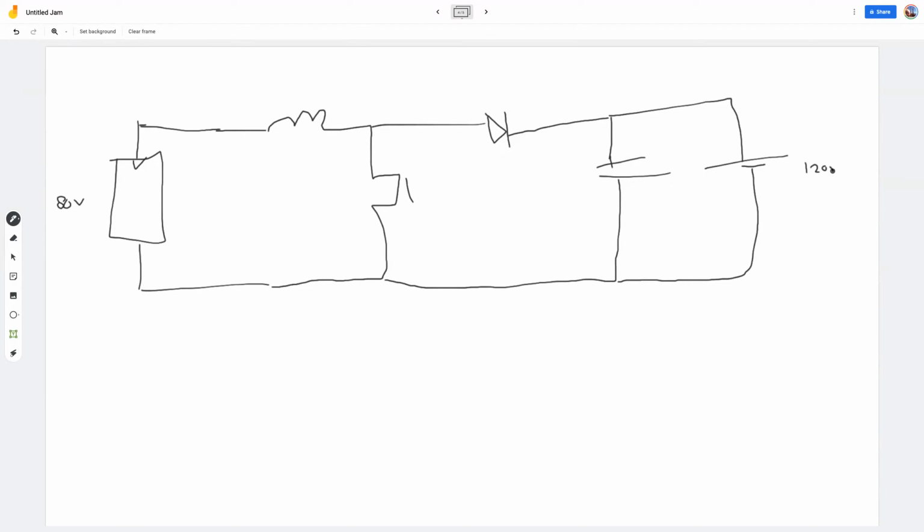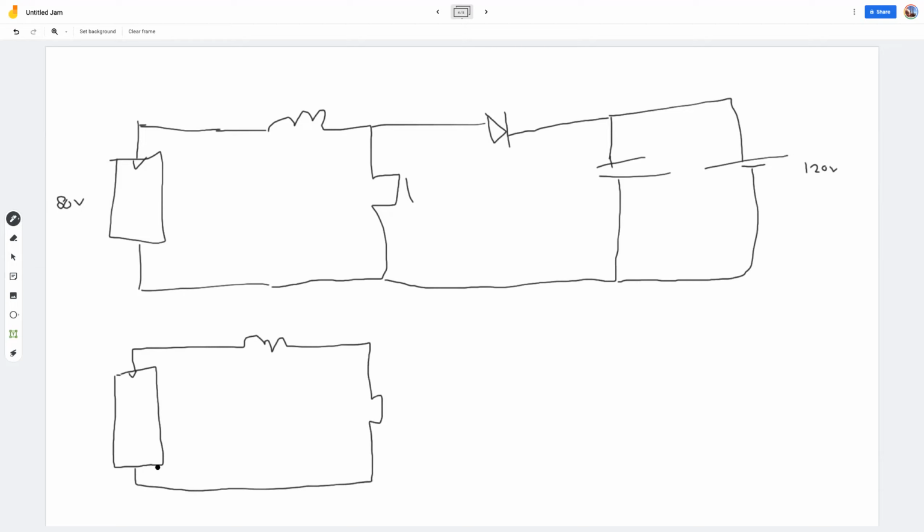A constraint of a maximum power point tracker is that the input voltage should always be lower than the output voltage. So with the series MPPTs, you would, based on a boost converter as well, I'm going to draw a second boost converter. So what you could do, you split the array in two groups of two MPPTs you put in series. If you just put it in half, you would have two groups of 40 volts instead of one of 80 volts.